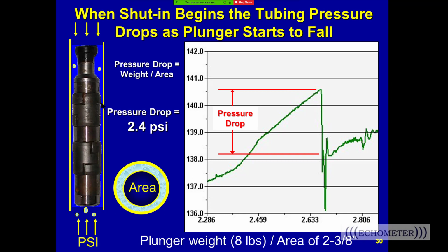I'm going to link another question from Manuel related to the same point. It is if you could mention again the sample rates versus the plunger type. If we have a table available, if not, just mention it. Fast plungers, you have to sample fast because they go really quickly by the collars, and you can't hear them if you don't sample fast enough. It just looks like noise. So you have to sample faster, and you also can't hear the plunger usually, probably over half the time, once it falls into the gassy fluid column.